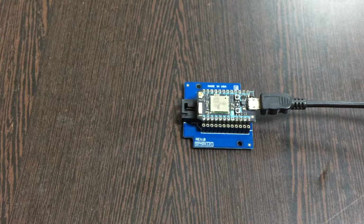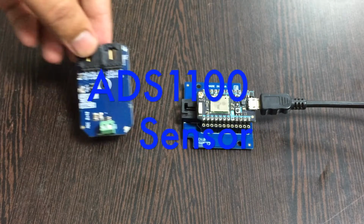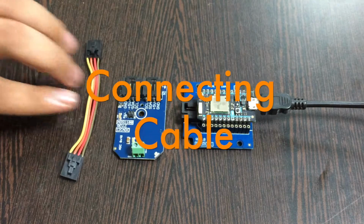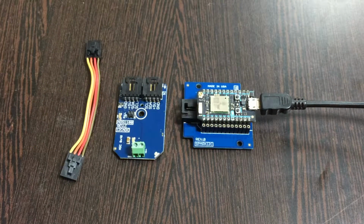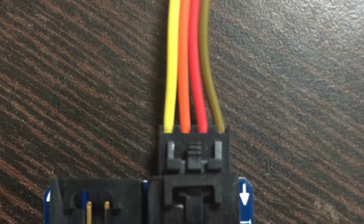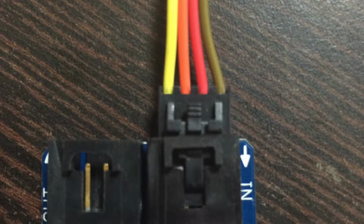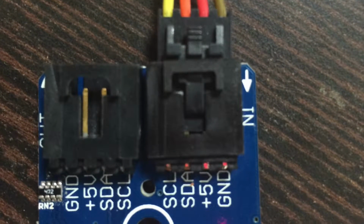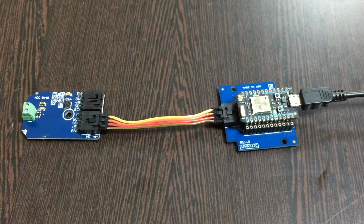The next thing we require is our sensor, that is ADS1100. Now this here is a connecting cable. Now this connecting cable is very useful in making connection with the sensor and the I2C shield, and making this connection, make sure that the ground terminal of the sensor should be connected to the brown wire of the cable, and similarly to the I2C shield, just like that. As we are done with all the connection setup, what we require next is to have a look over the code.